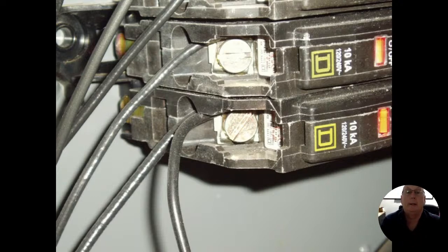All right, Square D breakers. And more so, we're going back into the panels a little bit. One of the usual suspects that we find doing home inspections are double taps. I want to say just about every panel that we see is going to have 2 wires under a lug. And sometimes it's okay, and sometimes it's not okay. I'm pretty sure there's other breakers out there that are designed to carry multiple wires under one screw, but right now, the only ones that I ever see are the Square D breakers.